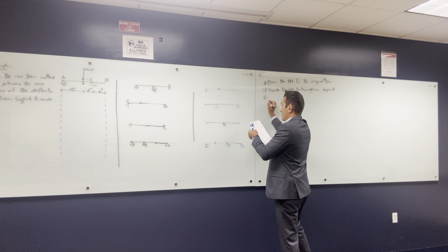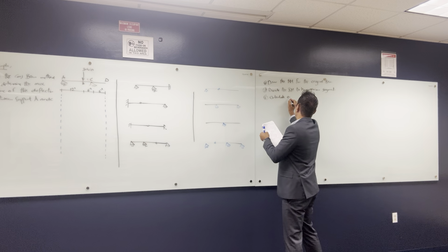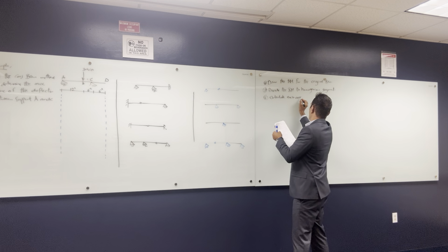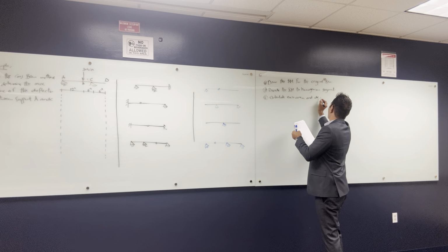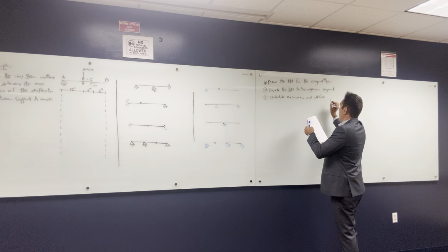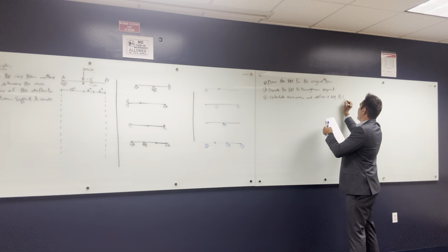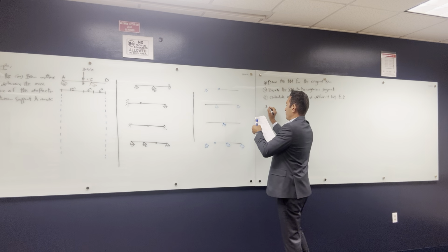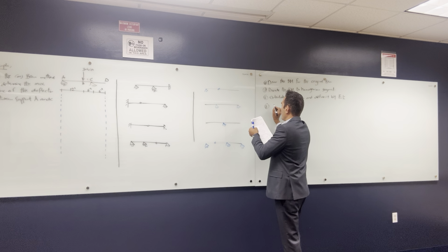Number three, calculate each area and divide it by EI. Number four, find the elastic load point of application.